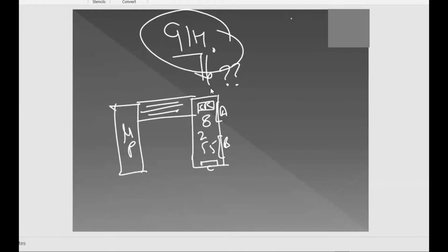They do not have any ALU or any other decision making circuitry. What should we write, 0 or 1? So somebody has to provide this command to 8255, and who can do that? Only the microprocessor can do that. It will load this 91H via data lines inside the 8255. And 8255 can further interact with the peripherals via ports.